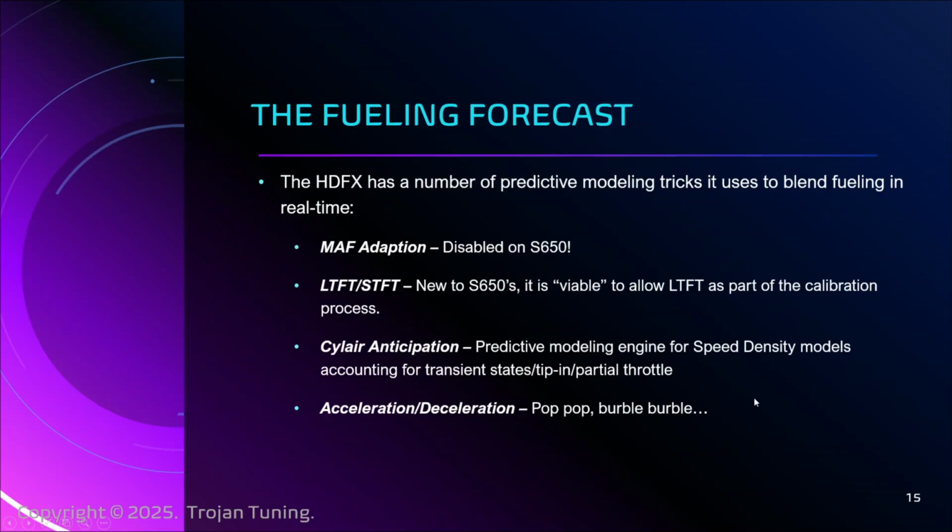One of the other things is the deceleration tracking, right? So if you are pushing a lot of fuel in a rich state through the engine because you've been commanding power, and then you suddenly let off the throttle, you've got a lot of fuel as that door closes, right? There's still some extra fuel left over, and it's a mist, right? And that mist moves through, it doesn't get combusted, and it hits the hot exhaust, and guess what? It's a vapor. It's hot, right? Pop, pop, pop, pop, pop. It combusts.